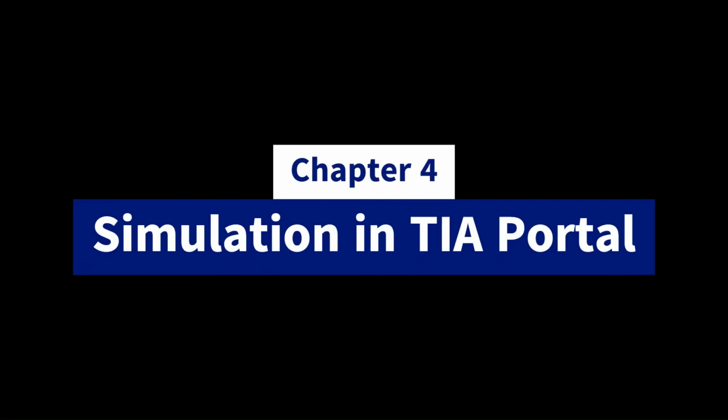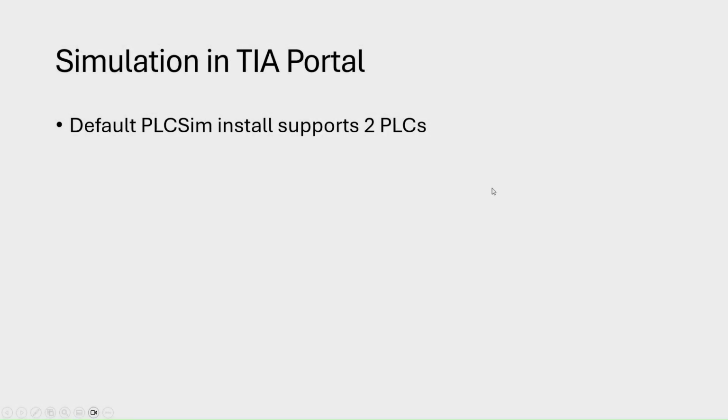In this chapter, we will explore how to do the simulation in TIA Portal. So all of the previous information or theory of the digital twins, how should we actually implement that in TIA? So in TIA Portal, as you may know, there's a PLC Sim also installed, and you can use that part of the software to simulate a PLC instance.